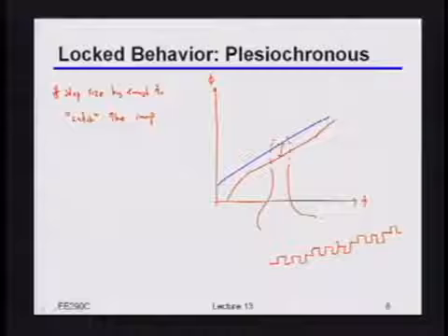For those of you who like to think of things in, let's say, a 240 or even 140 kind of context, that step size is setting the slew rate of the loop, right? If I know how fast that loop is updating and what the step sizes are, I know the fastest thing I can possibly catch. So the step size has to be big enough that my slew rate can keep pace with the slew rate implied by that frequency error. Does this make sense to people? You can either increase the step size or increase the update rate. That's right.